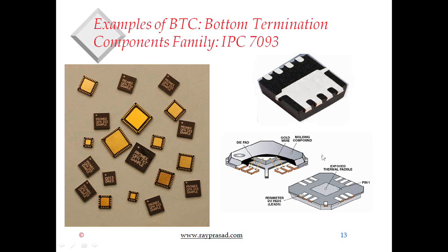And if you turn it over like in these other pictures, that's just the bare copper that can be plated. Obviously, the bottom side is generally plated with, in case of lead-free, it's without the lead, and in case of tin lead process, it has the lead in there. And that's what reduces the cost, because essentially you have a sheet of copper that has silicon on top of it, and then molding compound, and you're not dealing with the bending of leads, putting of the balls, any of those process steps, and that's why the price is low.